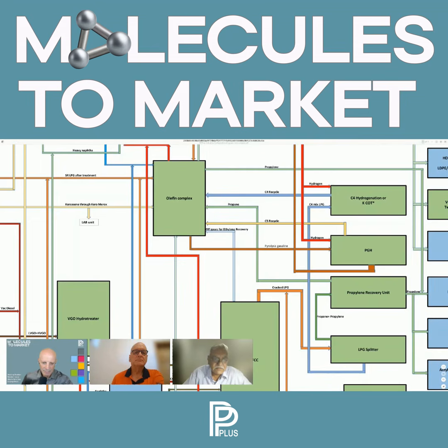Third part is about power. Anytime the site is selected, we have to see that to build the plant, till such time as you have your own captive facilities, we need a substantial amount of power during construction. So there has to be a mechanism for it. Either you set up plants which are, let us say, diesel generator based, so that you can have lots of power from there, or possibly you could have a grid, and from the grid you could tap the power, create a small switchyard, and then distribute power into various substations within the complex, which could facilitate construction activity.